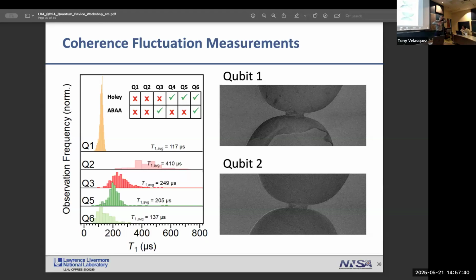You mentioned that you're using argon ion milling in the process of removing native oxide. I've also noticed from my research that ion milling can actually harm the substrate. The sapphire substrate creates a layer of amorphous sapphire-ish material that reduces your overall coherence. So how do you approach this problem?